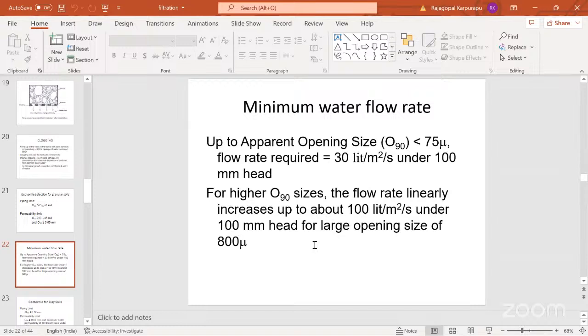Yeah, that's a good point. Actually, we do not directly place a geogrid on a clay soil. We always put a working mat of at least 300 millimeters thick. On a clay soil, we put a geotextile separator, then place at least 300 thick aggregate, and then only place the geogrid.